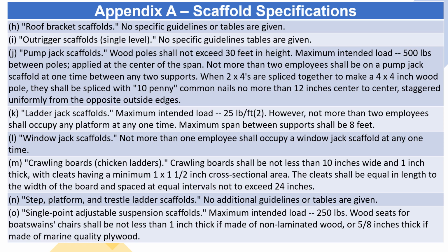N. Step, platform, and trestle ladder scaffolds. No additional guidelines or tables are given. O. Single-point adjustable suspension scaffolds. Maximum intended load 250 pounds. Wood seats for bosun's chairs shall be not less than 1 inch thick if made of non-laminated wood, or 5/8 inches thick if made of marine quality plywood.